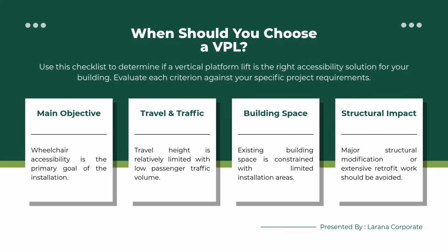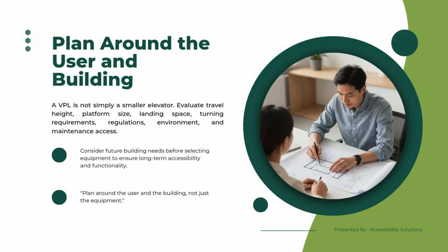Conclusion. So, what is the best elevator solution? For an existing building, there is no universal answer. An MRL elevator may solve machine room limitations. A traction elevator may provide better energy efficiency and performance for multi-floor buildings. A hydraulic elevator may be suitable for certain low-rise retrofit conditions.